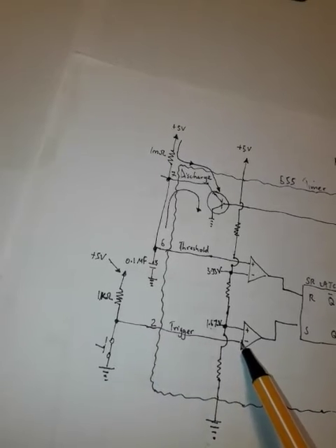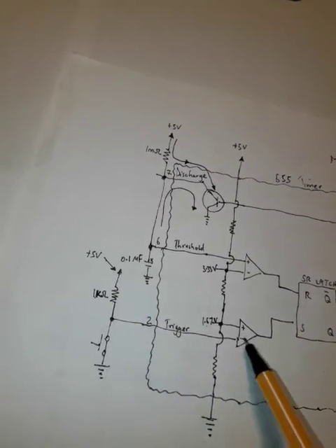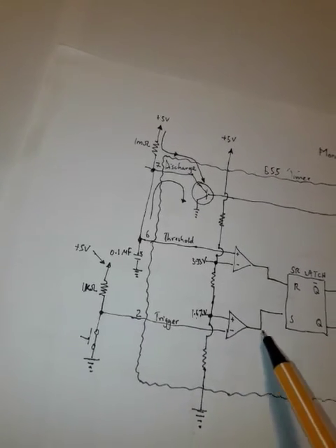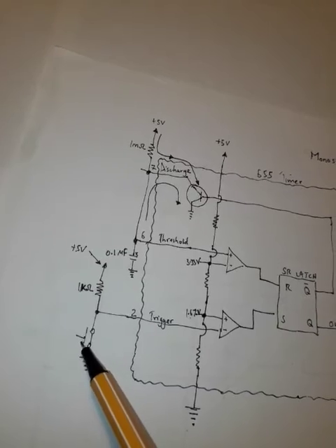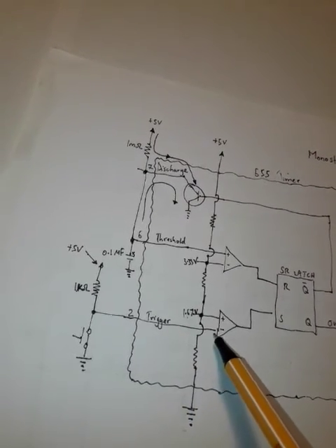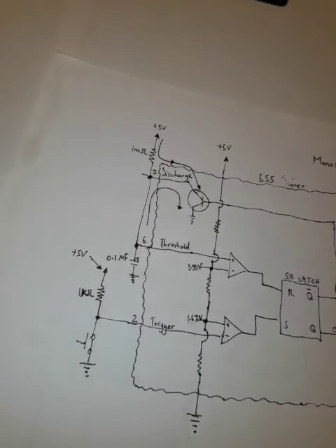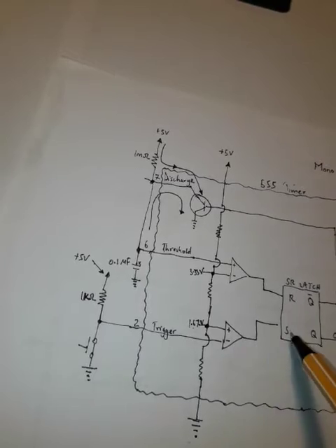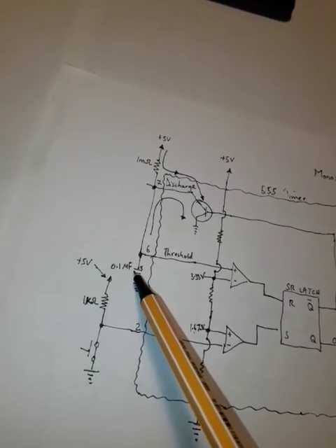And once this is set again, it means our button is out, and therefore we are back to 0 volts on this side, and our trigger is having 5 volts, and nothing is going to happen until we push this button again. So once we push the button again, this trigger will have 0 volts here. The comparator sets it. We have the output, and while it's on, it's charging this, and the capacitor is providing enough charge for that.